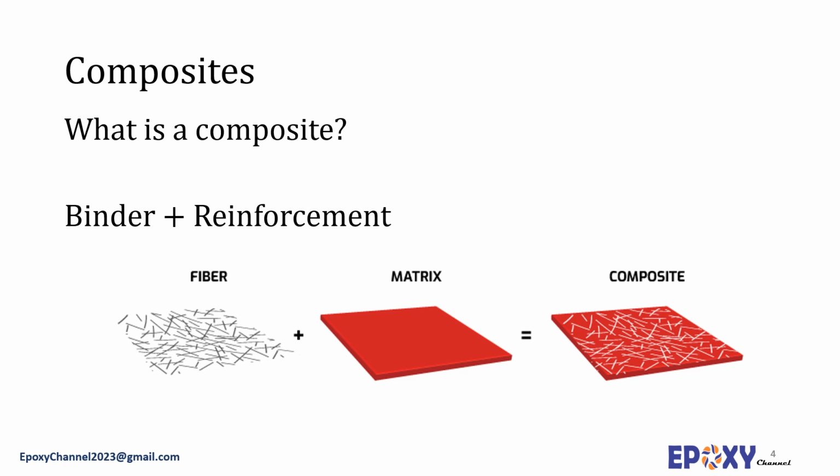Composites are a blend of two or more components in which one component is for reinforcing, often fibers, and the other component is generally made up of a resinous binder or matrix that is polymeric in nature. These components both retain their individual identities and directly influence the composite's final properties. The resulting composite is composed of layers or laminates of fibers and matrix stacked to achieve the desired properties in one or more directions. Composites are generally orthotropic materials having different properties in two different directions.